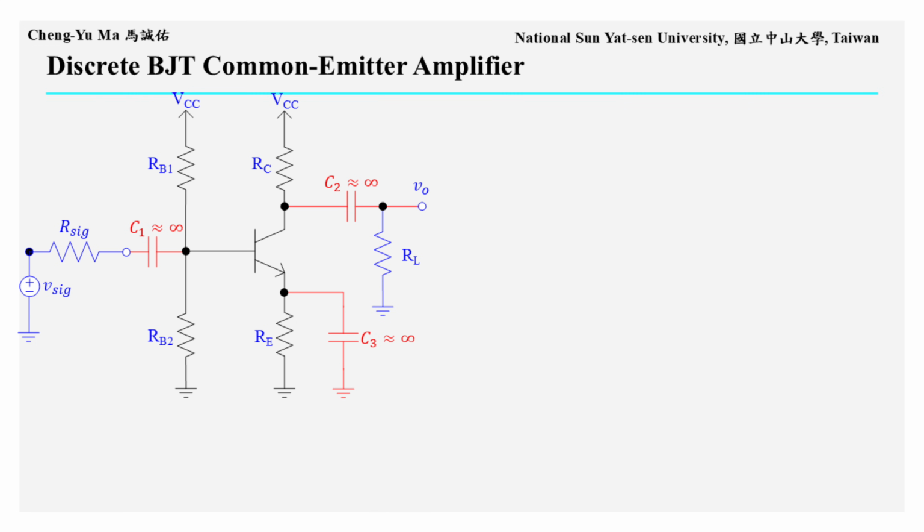In contrast, an integrated circuit, or IC, means that all components are fabricated together and connected internally during fabrication, so the components are not detachable. Integrated circuits also usually avoid large coupling capacitors because they take up chip area. Returning to this circuit, the input signal is applied to the base terminal, and the output signal is taken from the collector terminal. Therefore, as discussed in the small signal analysis chapter, this is a common-emitter amplifier.